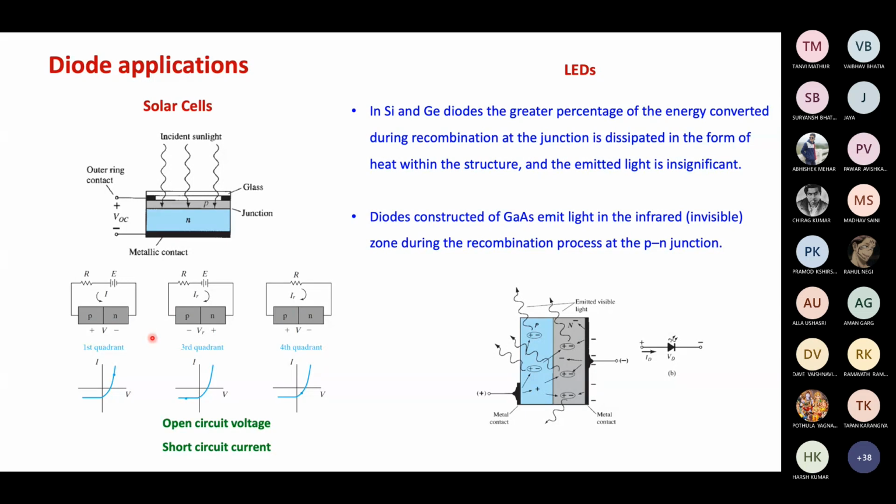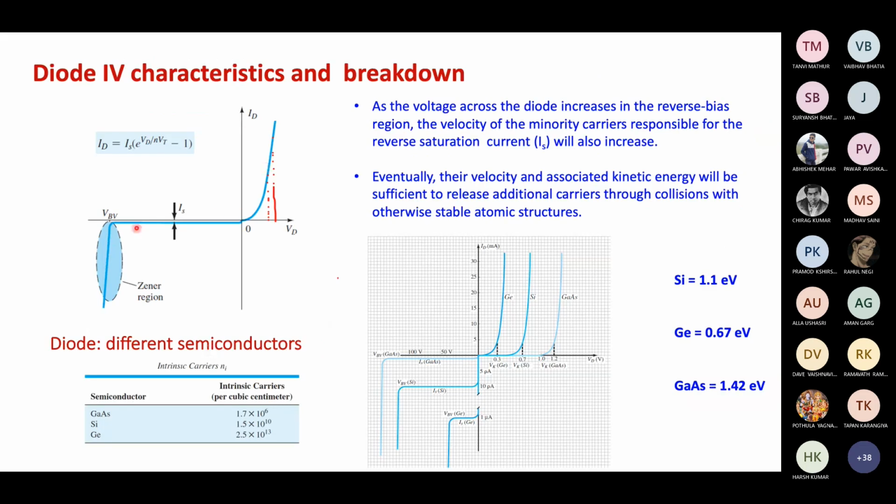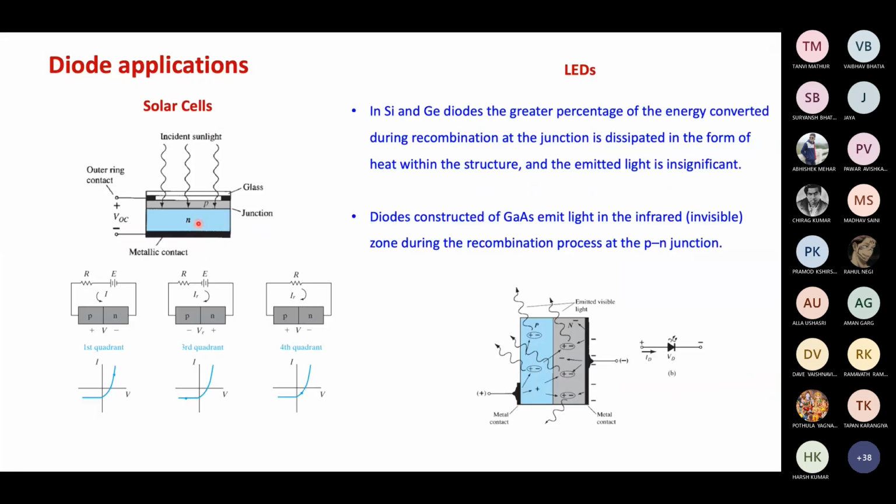Yes, sir, that is clear from this. Actually, that can be cleared from this diagram. So this is the typical IV characteristics, without light. So in reverse bias, let's say the diode is operating here. But as soon as the light falls, the current will increase. The negative current will increase if the voltage is kept constant, like this. Okay, so that can be understood from this plot.